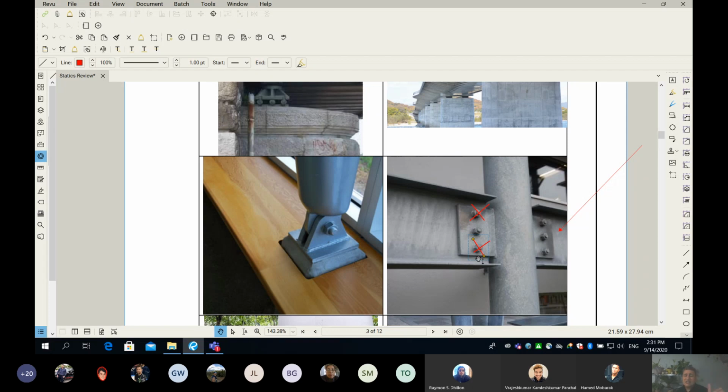But this is in the book. In reality, in engineering, the way we do it is, if we connect the flanges to the column, it means this is a moment connection, because most of the moment or the rotation will come through the flanges. If we connect the web, we do it only as shear, and we don't think of it as restraining the rotation. I know it could be complicated, but it is exactly what I said. Engineers look at this one and design it as a shear connection, so it means rotation is allowed.